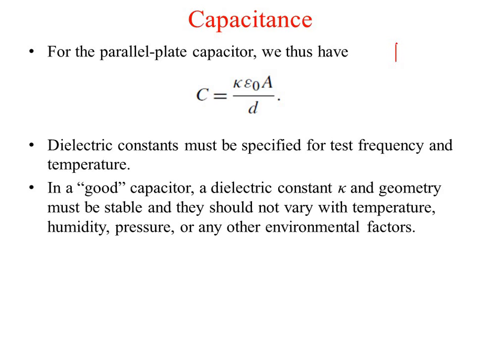So there was a tuning factor like this one, and these are the plates. These are the plates like this, and these are tuned to a particular rod, and I used to change this in a rotational manner. So that used to change this cross sectional area, because the distance used to remain the same, but the overall capacitance changed.